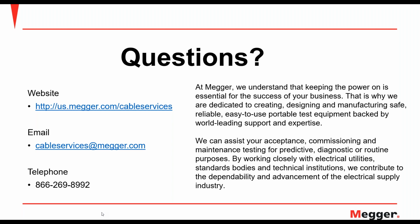Good question there. When testing a short run of cable, one issue is the capacitance of the cable. As you saw in one of my slides, we had the support capacitor there, so that we can always add capacitance to be able to test shorter runs of cables. So that's not really the limitation. The limitation, though, when you test these shorter runs of cables, say 20 meters, is really the localization of the partial discharge. That's just due to the cable length and the speed at which the signal travels through the cable, and you're really kind of limited.